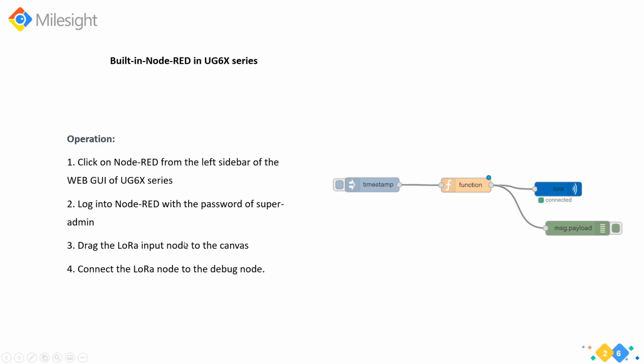I think one of the many joys of Node-RED is the very simple method of designing or importing designs, connecting code by flows. You can set up a Node-RED flow that listens to events and uplink messages, and also you can schedule downlink messages here. So you just drag the nodes from the left sidebar onto the canvas and then connect them by left mouse clicking on the input and output circles at either end. So click these small gray circles here in the picture.